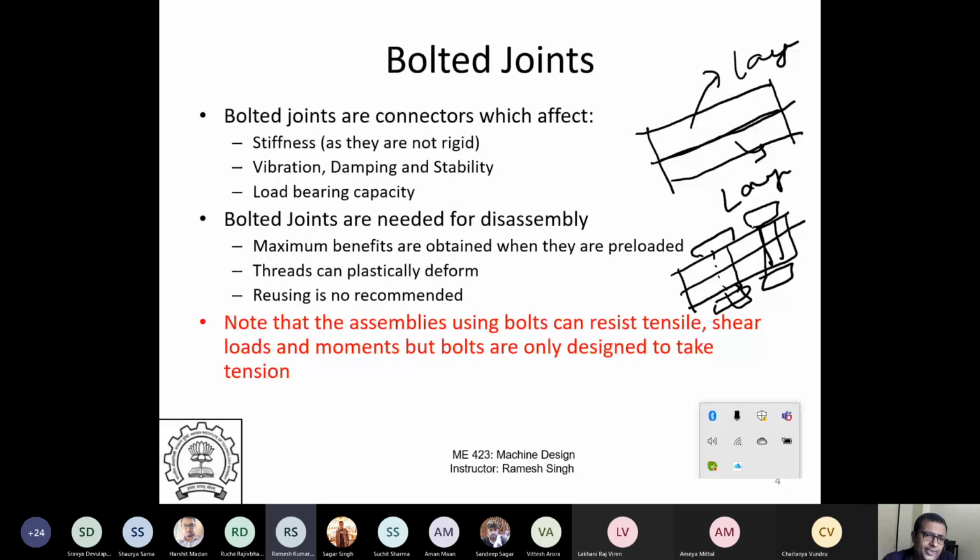What will be different? What would this bolt bring into the component? Stress concentration. Pardon? Stress concentration, some cases, but they have fillets and radii not to have stress concentration. So the issue is it will not be as rigid. This will have some compliance. If you do perfect bonding, you have rigidity, right? If you have bolted, you will have an additional compliance. Basically, the bolt will be a spring, and your panels will be another spring in parallel. So there will be a stiffness issue.